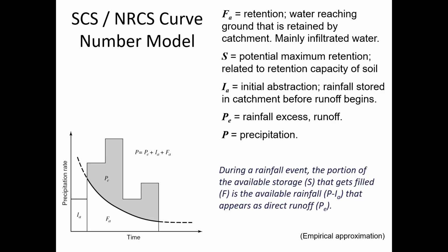What do you mean? Like, initially when it starts raining, there's no runoff. It has to go into the ground first, and the ground has to become saturated. You're right. Yeah. So you're definitely correct about that. There hasn't yet been any excess yet. So why not? Well, remember that this is the precipitation amount. So the precipitation amount was less than the infiltration rate. And so you're only going to see excess when the precipitation rate exceeds the infiltration rate.